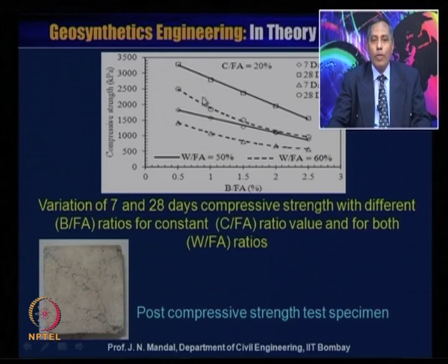You can see from here also that there is an improvement of the compressive strength if you keep the water to fly ash ratio at 50%, for 7 days and also for 28 days.